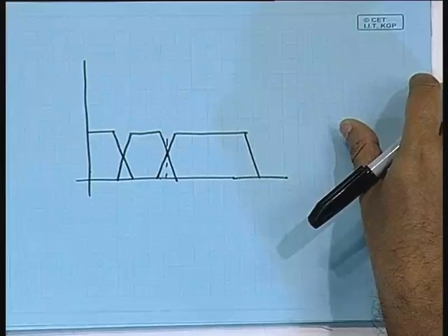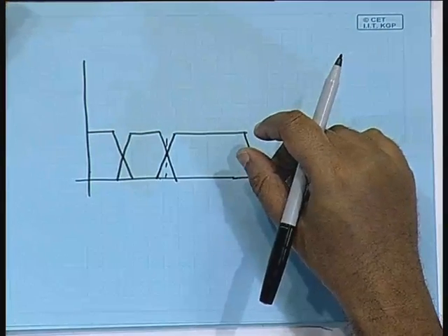So, that means the wavelet essentially permits us to realize a bank of analysis filters. Which means we can obtain the original signal back if we apply a corresponding bank of synthesis filters.